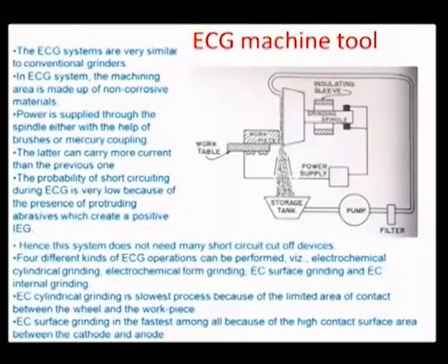There are certain other aspects associated with the machine tool as such. It has to be a rotor driven tool as any other normal grinding process, because there has to be relative rotation between the electrochemical wheel and the workpiece surface. So this slide here illustrates briefly how the electrochemical grinding machine tool would look. So you have a workpiece here, for example, and then you have a grinding spindle, and this is the grinding wheel, okay, and there is a flow of electrolyte past the grinding wheel.